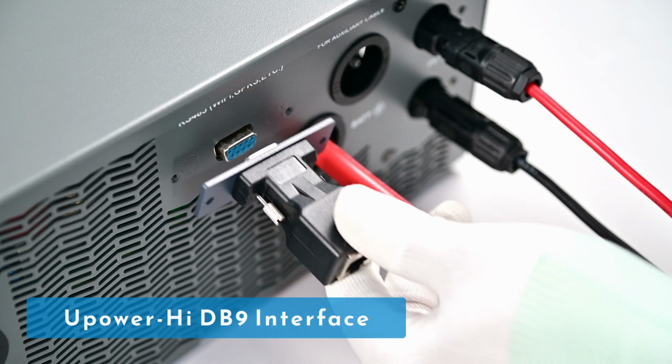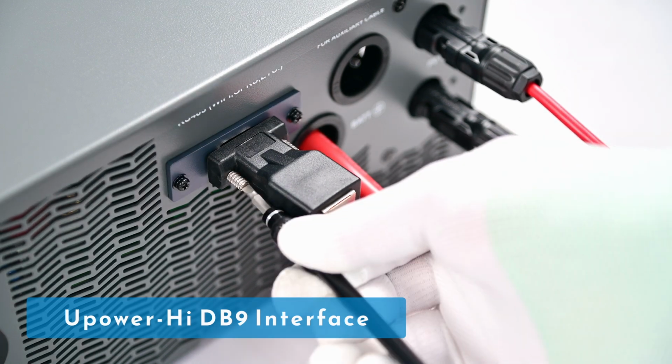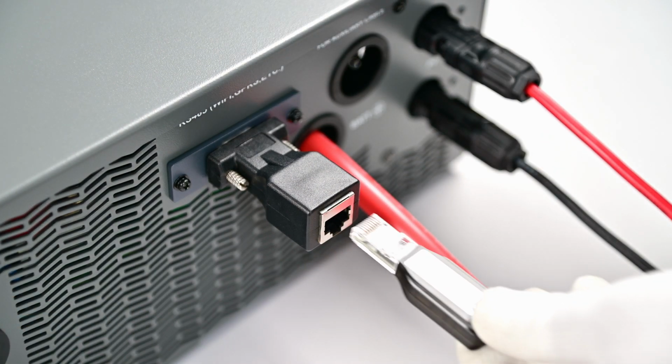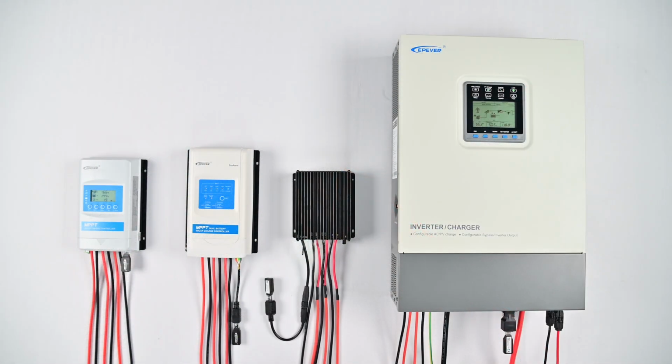Install the adapter to the U-Power High inverter charger. Then insert Gateway Module 4 into the adapter. Now that the Wi-Fi module has been installed, check that the device is working properly before proceeding to the next step.